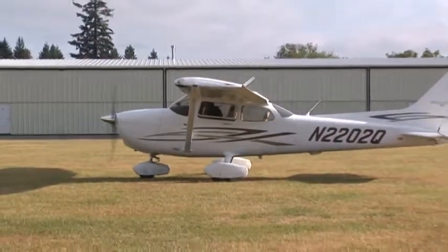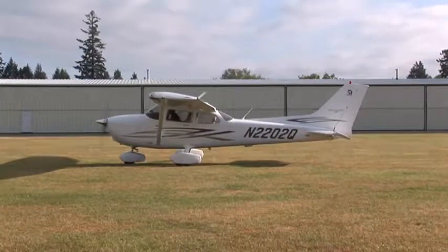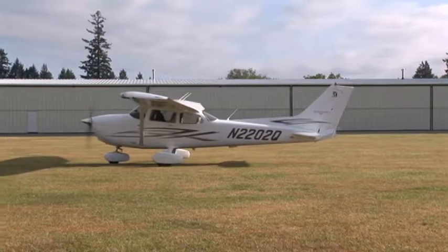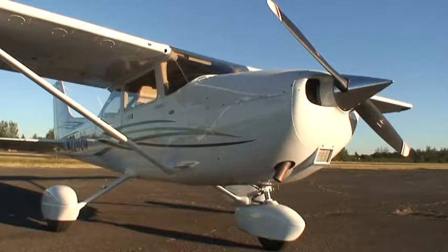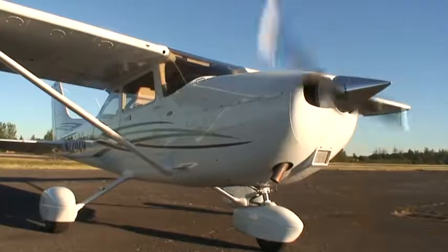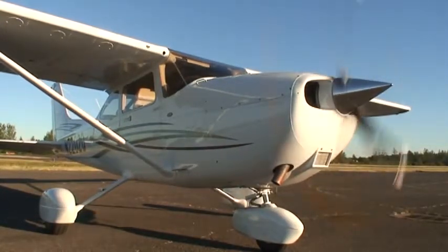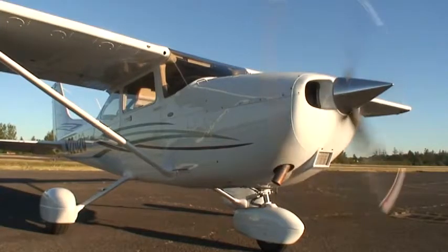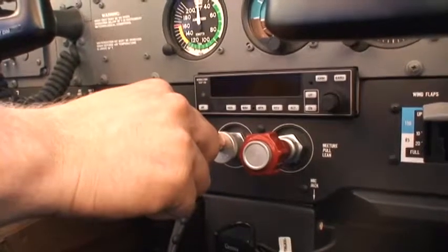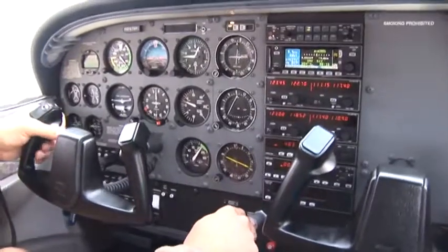We'll go into a little more detail on the operation of propellers. The crankshaft's rotational force or torque is delivered to the propeller. The propeller then converts power into thrust. Most small airplanes have what's called a fixed pitch propeller. A fixed pitch propeller has no mechanical mechanism to change the angle of the propeller blades while in flight. In airplanes with a fixed pitch propeller, power is controlled exclusively with the throttle. The amount of power is indicated by engine RPM shown on the tachometer.